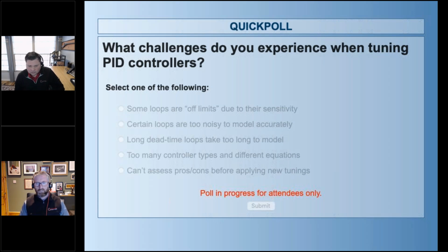Damien, do you want to assess the bottom two there? Loops taking too long is something where, for every step test, for every change, it takes 4 hours to do it, and for every manual change in tuning parameters, you have to wait those times to see what it's doing. That's going to be a tough ask. It can change a tuning from minutes into weeks, I suppose.